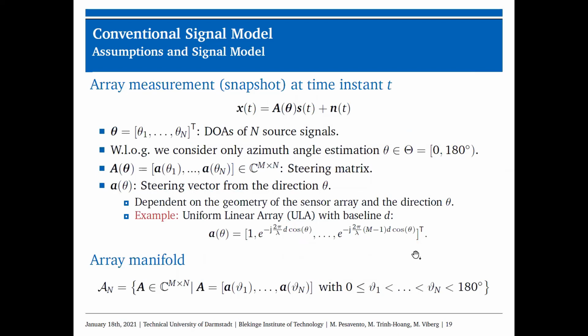So we need one more assumption, which is already mentioned, that the sensors and the receiver equipment all operate within their linear regime. Then the sample sensor signals will be a superposition of the contributions from each signal source. And under the mentioned assumptions, the sensor array output can be well modeled by the familiar equation shown here. X of t denotes the complex baseband sensor output at time t, and the matrix A of theta contains the steering vectors as its columns, and the vector S of t has the corresponding signal waveforms as components. The vector N of t represents additive noise, which takes into account anything in the received signal which does not emanate from the source signals.